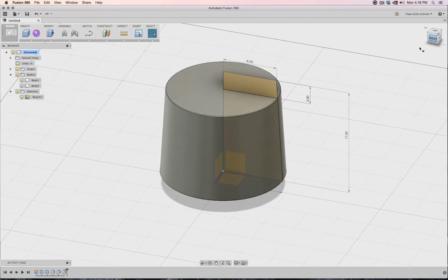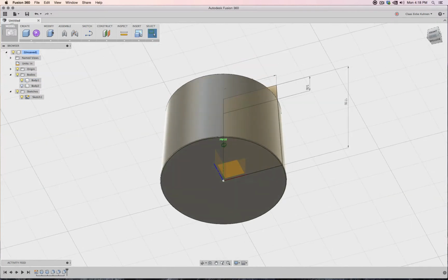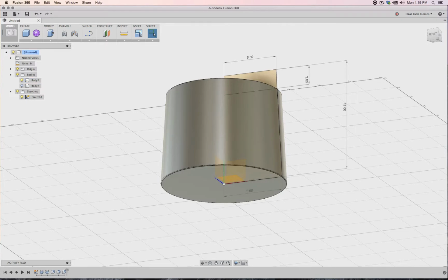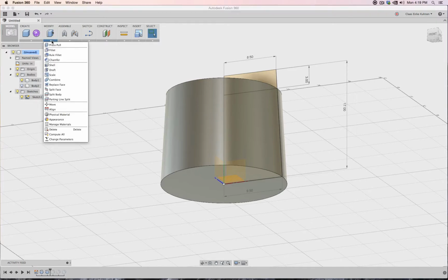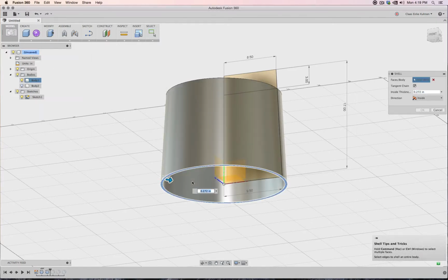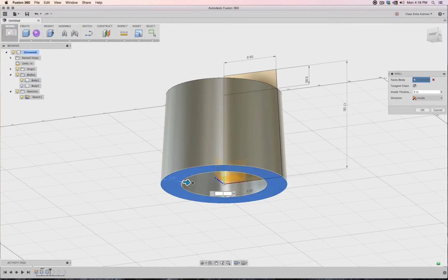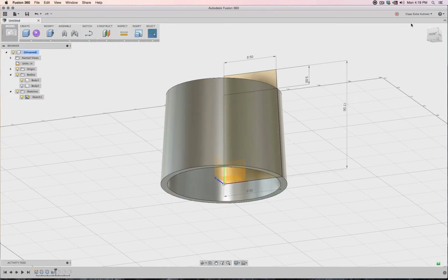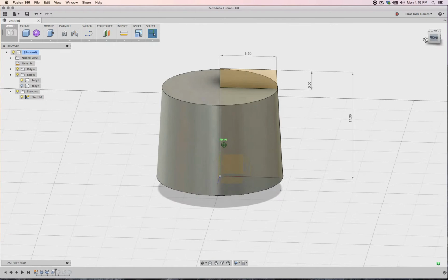Now, if I would give this one to somebody to build, they would see this is a huge piece of material, which we can core out. So, what I can do is simply, maybe this one. I move my cursor back to here before I have all these round edges. And I go to shell and say, shell me this one, maybe by 2 inches. Oops, too much. Let's say 1 inch. That's fine.